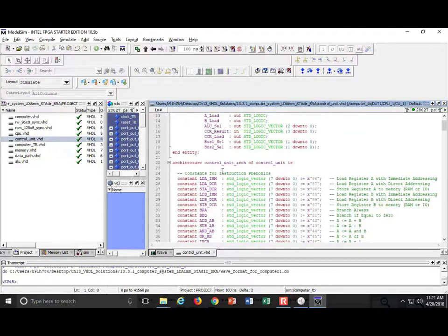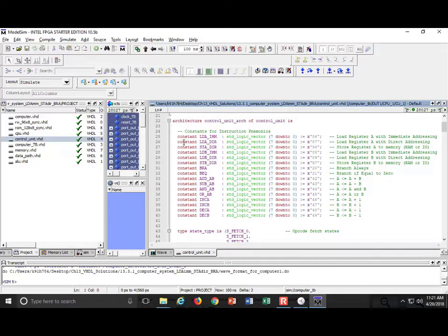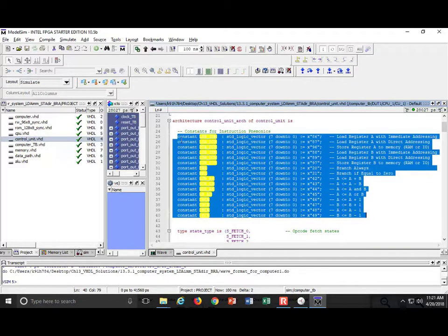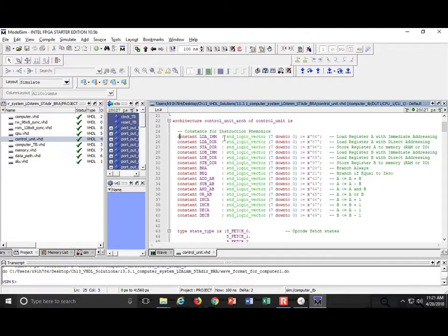When I look at this, I need to have the constant mnemonic table, which has the op codes for all these mnemonics. In this computer, you have to have it in 2 places. You have to have these codes in the memory system ROM and also in the control unit. It's a real cheap way to do it. It's not a global variable. It's not a global constant. I did them as local constants just to make it cheap. But they're sitting in there.